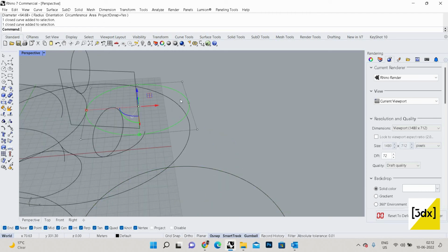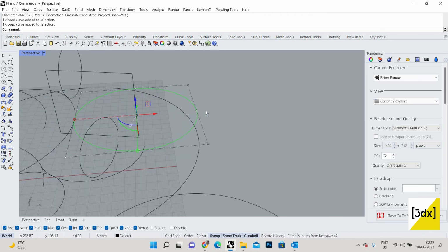Whereas this, you can see it's a grid. When I select this point, these points are known as control points. The control points are the major thing which controls the elements of 2D, 3D, everything. You can turn control points on or off with F10, F11. It's a shortcut key. Or you can use the show control points and turn off control points commands.